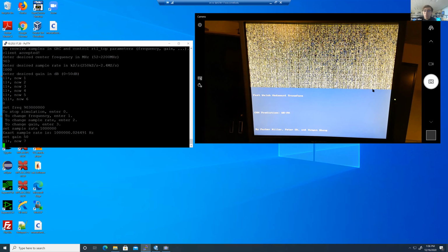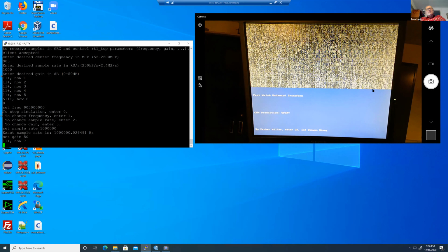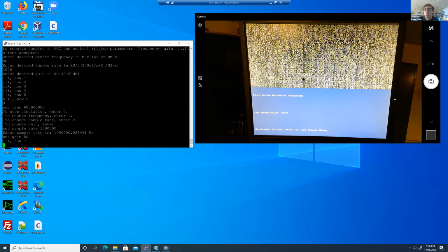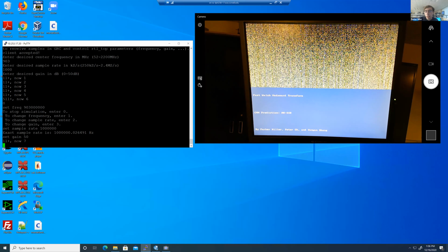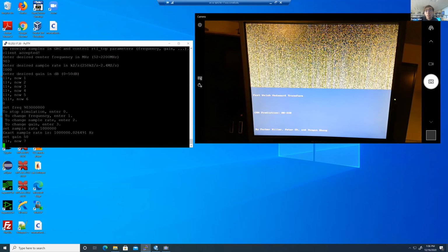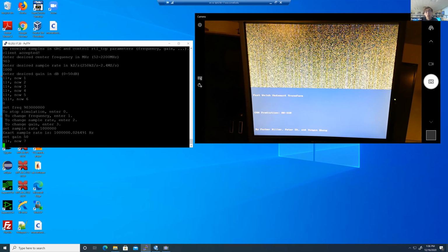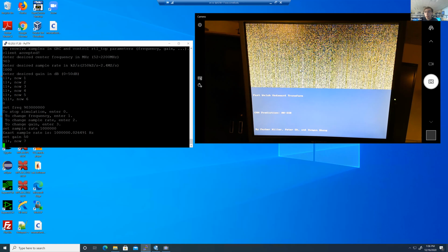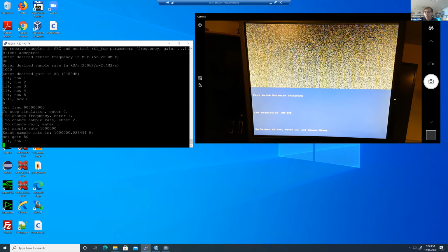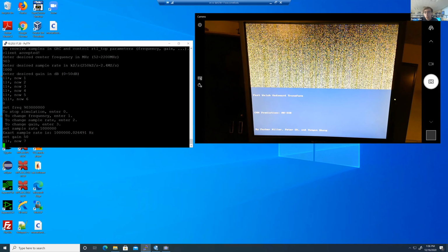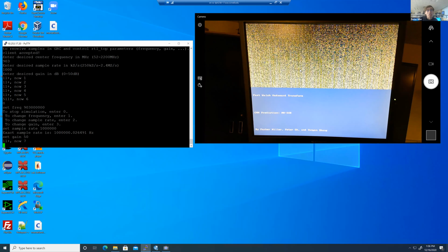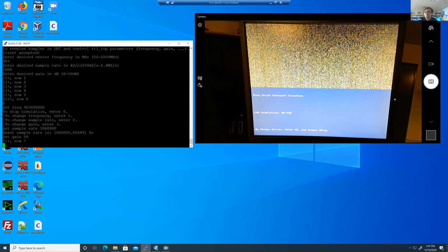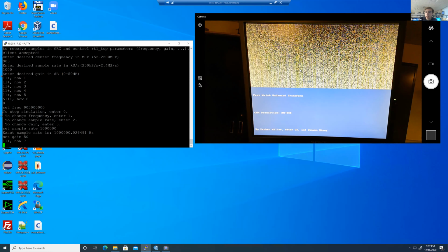Yeah. Very cool. Is that the Hadamard transform we're looking at there? Yeah. So that's the fast Walsh-Hadamard transform. We used it rather than an FFT, as it only uses real additions and subtractions, which are easy to implement and don't use as many resources as if we wanted to implement it with multiplies. We couldn't do a 128-point transform in 7 cycles.